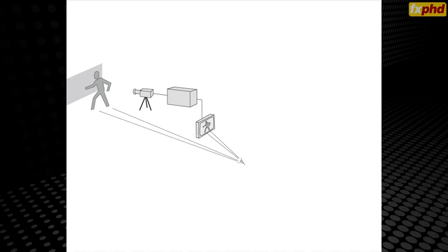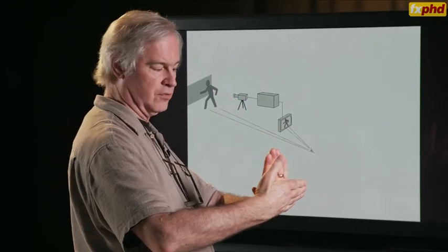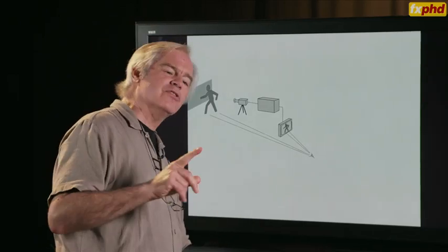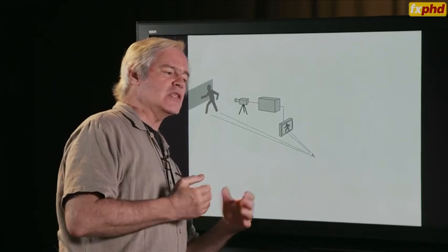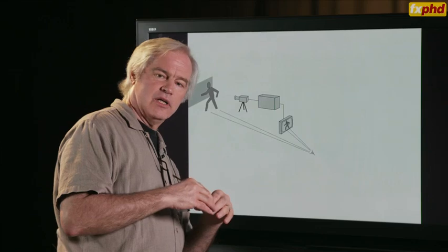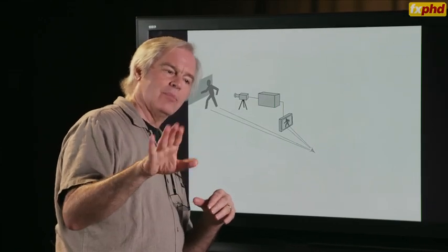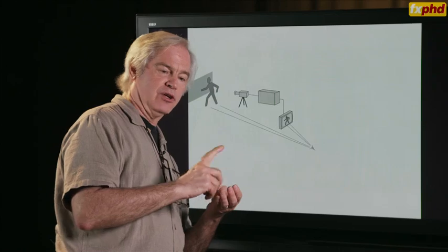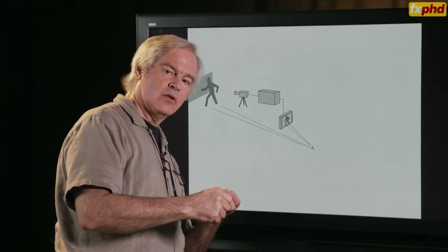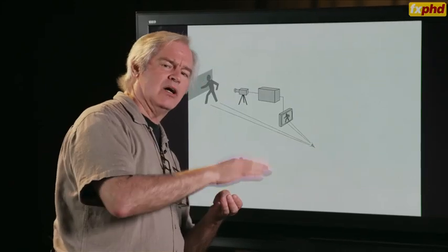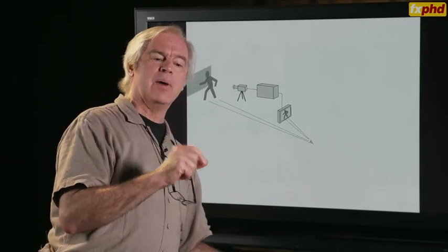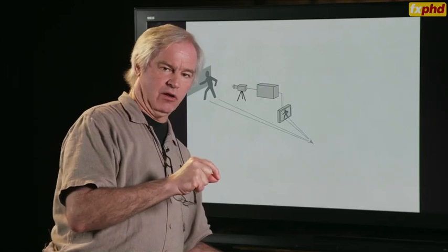That's what changed. All of a sudden we went from CRTs to flat panel displays, typically LCDs. And the main significance of that is that in the era of the CRT, gamma, or to use the really technical term, the electro-optical conversion function, the EOCF, just loosely speaking, gamma of the display, in the CRT era was fixed by the properties of the cathode ray tube itself.